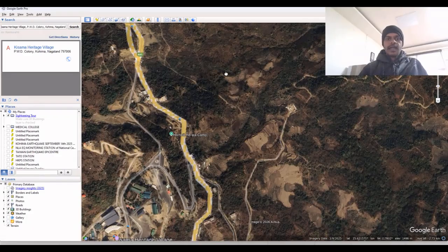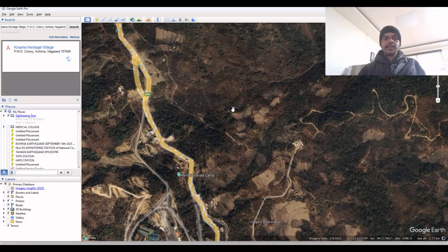In this video, I will be explaining a particular landslide and the process involved in processing the Sentinel imagery for detection of landslides, and I will also explain each and every step involved, starting from why we need the SLC images, not the GRD format, and what the steps involved are. What do you mean by TOPS split, what do you mean by apply orbit, what do you mean by back geocoding, what is meant by ESD, and everything I will explain in detail. So let us get into the video.